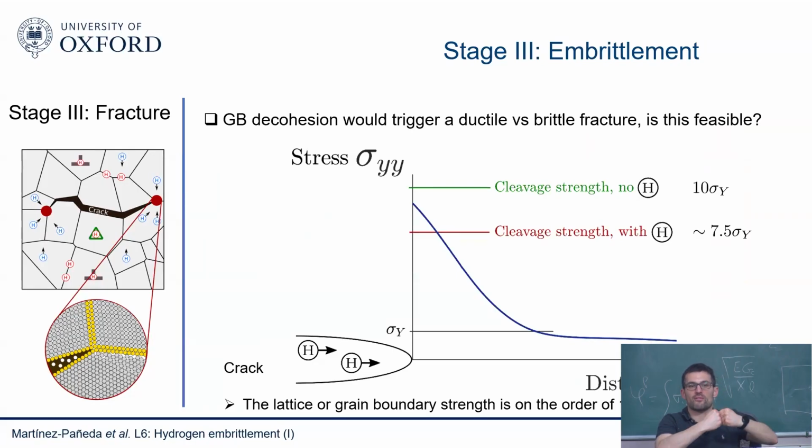Because we know that we have a bonding strength between grain boundaries, and our stresses are never big enough to reach that bonding strength. That's why we need these voids to nucleate, grow and coalesce. That's why we get ductile fracture processes. But it could be that eventually, if your stresses are big enough, this kind of mechanism gets activated before the other. It's a competition.